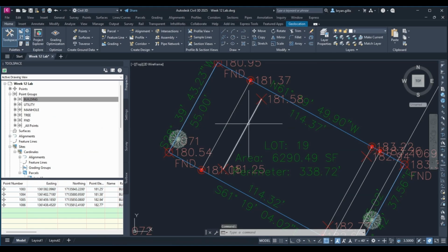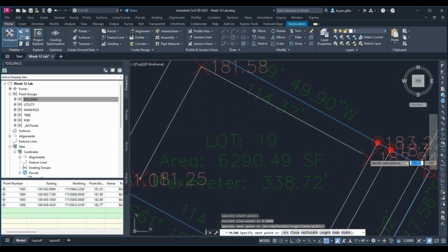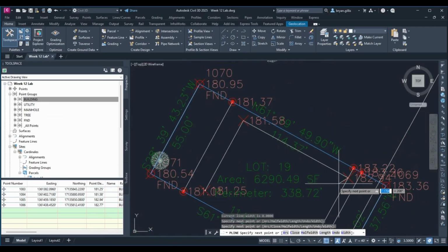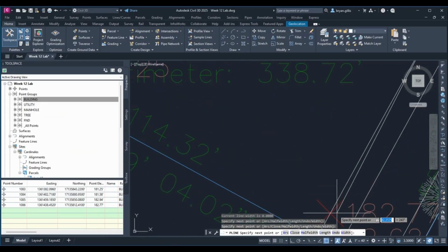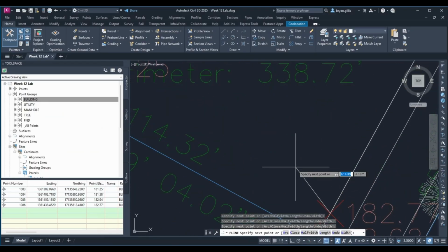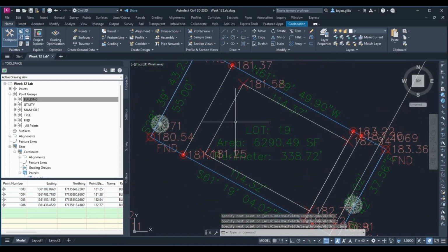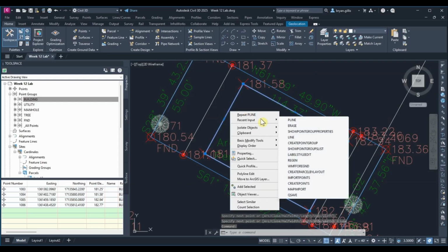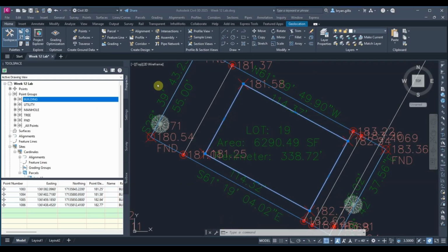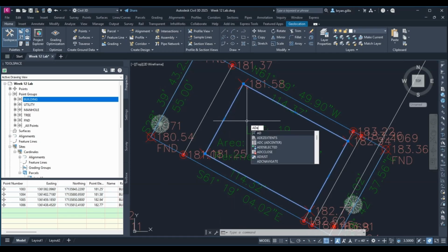And then I'll delete this one feature line that I did draw. I'm going to redo it as a polyline. This is going to help give me an actual polygon for the building whose corners we shot in. For those of you who think, oh, homes aren't truly this square, yes, they are. Many homes are this square. There's not a lot of character sometimes to their exteriors. So that's all we're really looking at here. We've now got our building outlined.